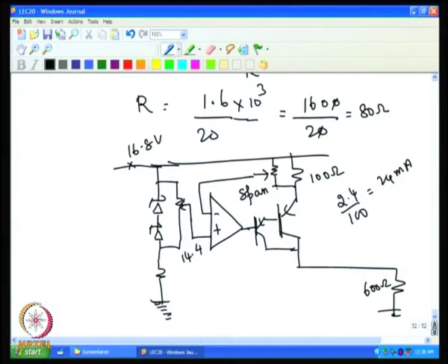Now, to reduce the current, what we can do is we can move the pot a little closer, or need not go up to the end. We can go here and keep it; with 100 ohm we need only 20 milliampere. So, one can move this away such that the voltage difference is only reduced, because this voltage and this voltage try to reach the same point. So, one can adjust this potentiometer and this resistance such that whatever combination we want we can achieve.